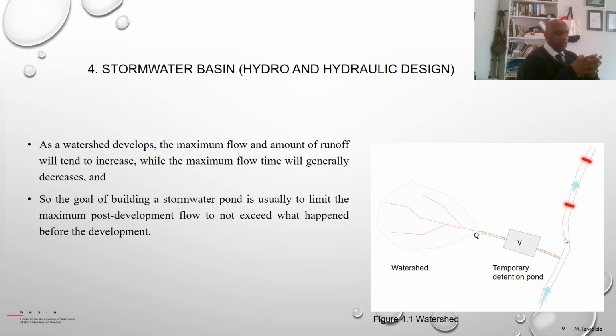We elongate the period for the peak to arrive at its peak discharge level, and we also allow the water to infiltrate or evaporate so that it will be decreased in volume as well. As a matter of fact, the runoff volume coming from the catchment area may not be reduced because we build a detention basin.